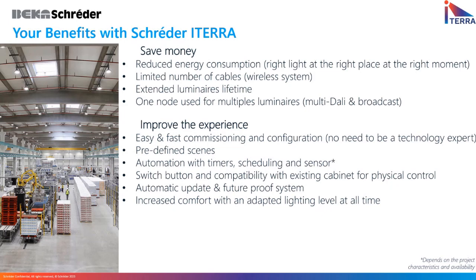So through the usage of the system, we can then also save the lifetime of the luminaire itself, because if a luminaire doesn't have to run hot and at full capacity all the time, you reduce the usage and extend its lifetime, not only through the LED, but also the driver that runs the LEDs.